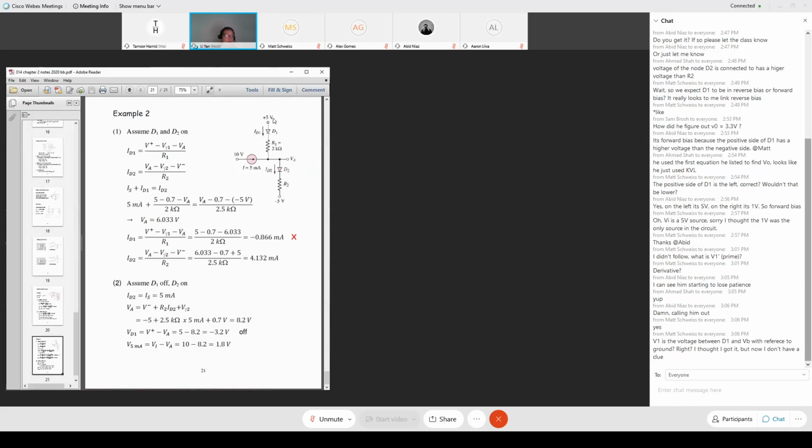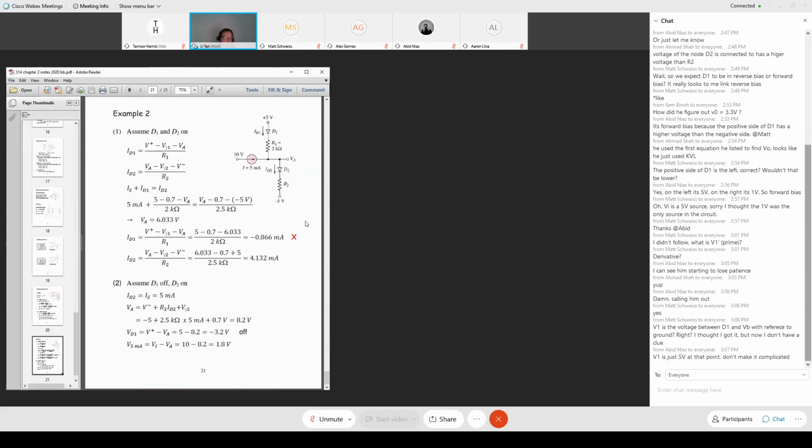Of course, you can ask why we say volts at this point when there is a voltage. Well, in this circuit there's a ground, and that ground is not shown. So somewhere there's a ground; between this point and that ground is 5 volts, and between this point and ground is minus 5 volts. Between this point and this point is 10 volts. So that's just the ground in the circuit. You're supposed to learn that from your 306 knowledge.